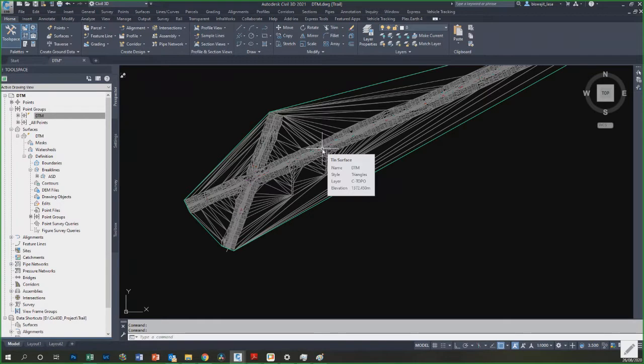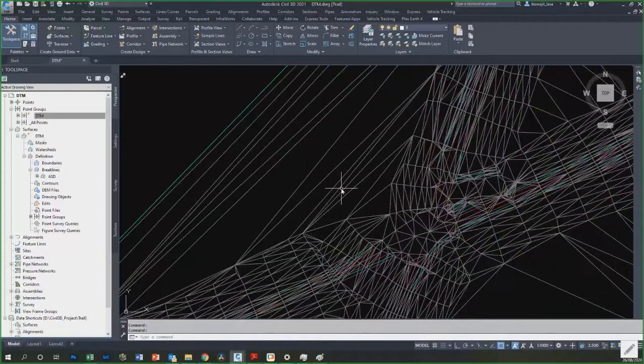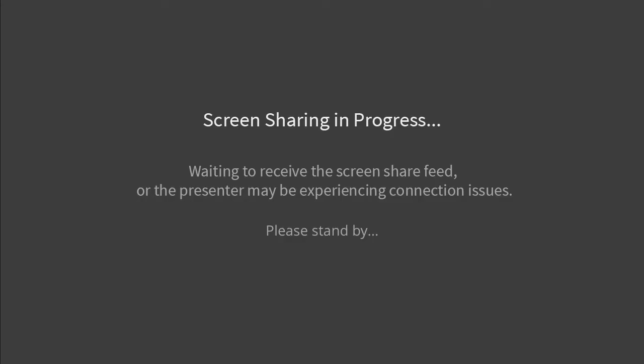So what I'll do is, the thing is you can leave this survey as it is here also, but if you are doing it, these triangulations will give you a wrong elevation difference. So it is recommended that you clear up these lines. There is an automatic process of clearing also, but that I'll show later.